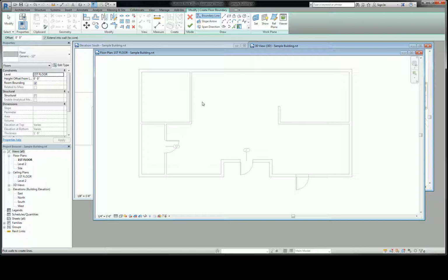What you're going to usually have is like a slab edge that looks like this, right? That's concrete. Fancy concrete. And then you're going to have your stud, sill plate, and then you're going to have the studs go up from there. And then your exterior sheathing is going to come down outside of that, right? And then your grade will be like there or something like that, okay?